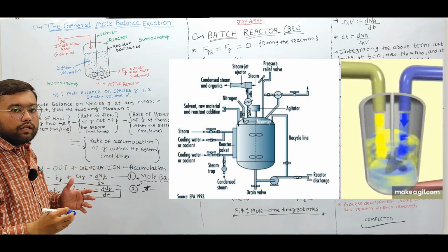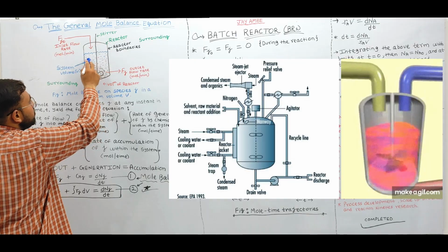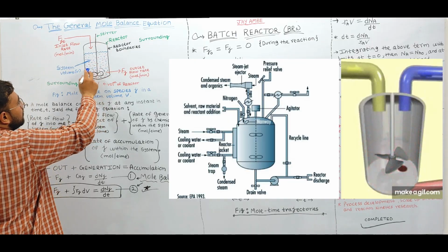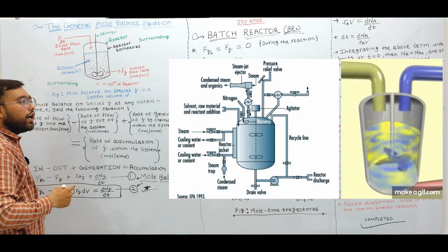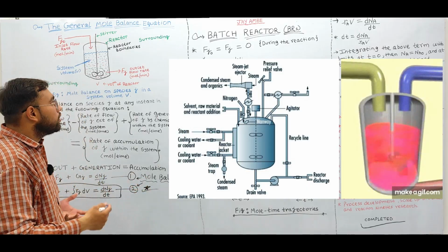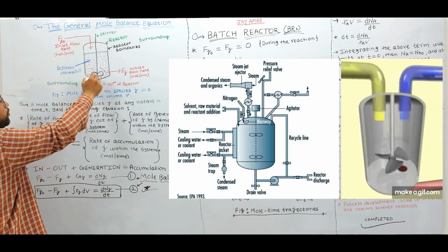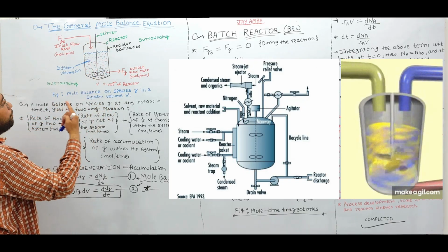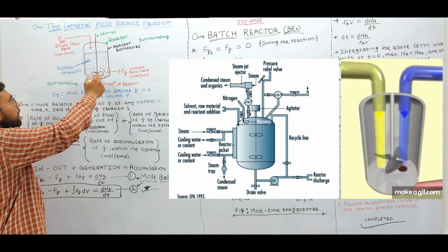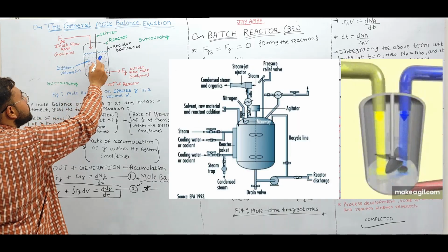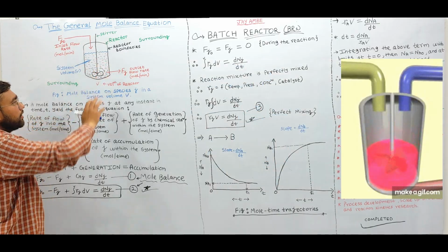In order to maintain the uniform distribution of temperature, concentration of species and the catalytic activity, we use an agitator or stirrer to provide thorough mixing inside the reaction environment, due to which we have uniform distribution of concentration of reactants, solvent and catalyst throughout the entire reactor volume.